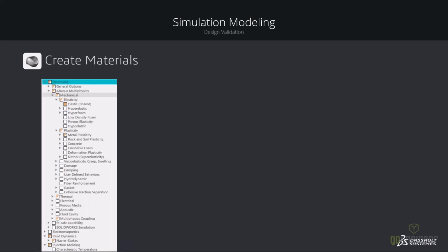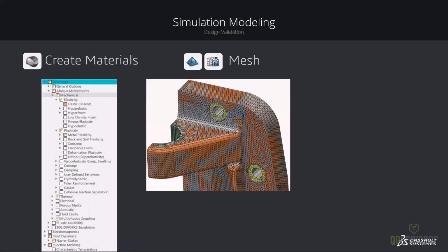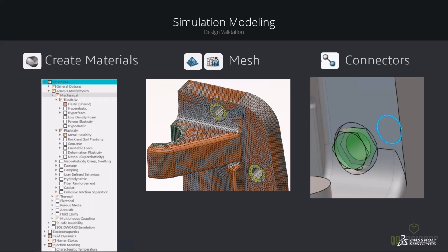So to summarize, in structural model creation, we assign materials with the material library. It contains a wide variety of material models and serves as a one-stop repository of material information for all simulation domains. Next, we assign tetrahedron and hexahedron meshes simultaneously in complex geometry using the partition tools. And finally, we restrain the model with the powerful bolt connectors and finish construction with couplings and connector elements.